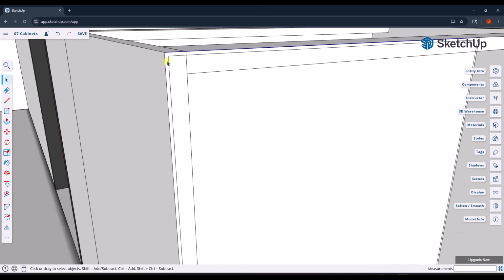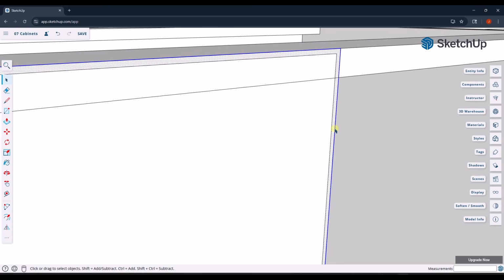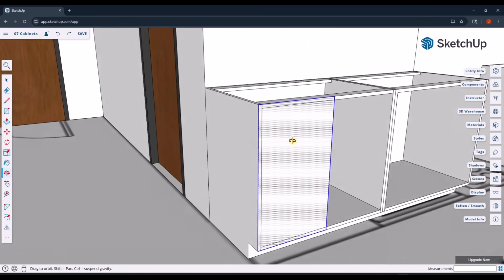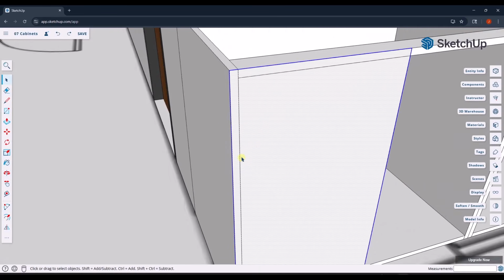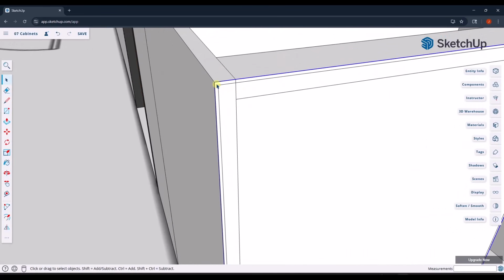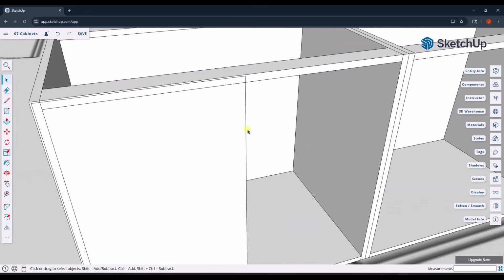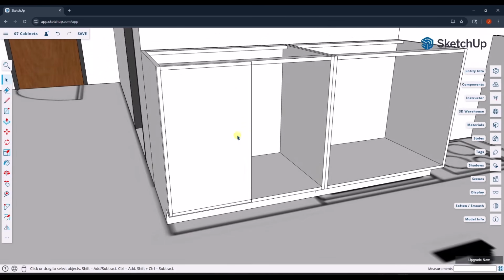So what I'll do is I'll double click on this face and then I'll do a shift double click because that'll pick up this face and its surrounding edges. But then I do a shift double click again and notice how it deselects this face and the surrounding edges like this. Well, now all I have is this extra face and this extra edge selected. So I'll run through that one again because it's a little bit tricky. So basically the way that works is double click, shift double click, shift double click. That deselects this face and then I can just hit the delete key and you can see how that's going to erase out this edge right here as well as the extra face, so that you don't have a bunch of extra geometry in here.